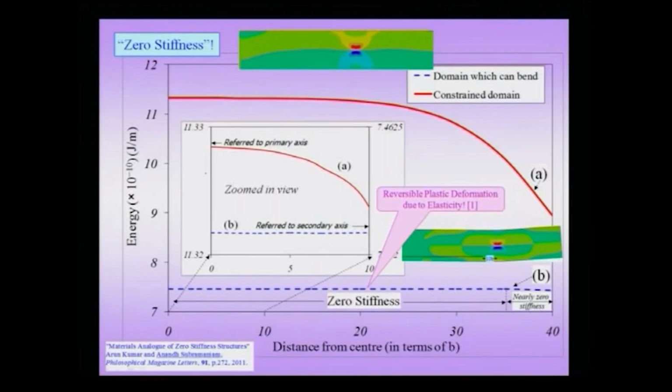Now, an additional interesting thing is that normally, as we pointed out in the previous case, when you have a dislocation, it feels an image force towards the free surface. That means that suppose I take a crystal and plot the energy of the crystal as the dislocation is positioned towards the free surface, the energy would decrease as shown by a curve like this. So, it is decreasing always, and finally, of course, when it leaves the crystal, it creates a step.